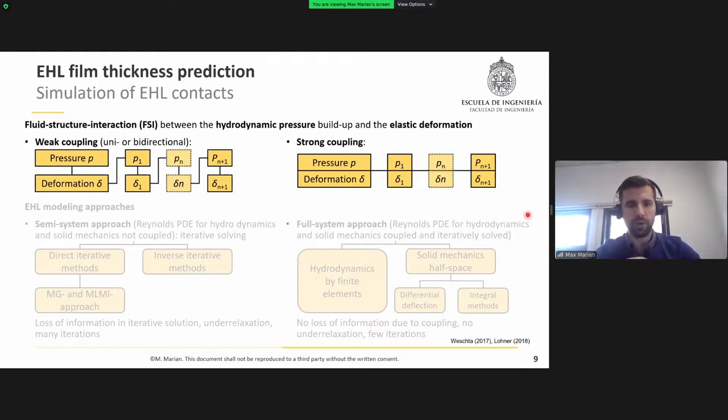In this case, however, the lubricant has to be meshed in the gap height direction also, which makes normalization and mesh transformation quite difficult, and usually we have quite some instabilities there due to an over-response of the elastic deformation to the surface pressure of the previous iteration step. Therefore, the hydrodynamics is most frequently represented in the form of the Reynolds differential equation.